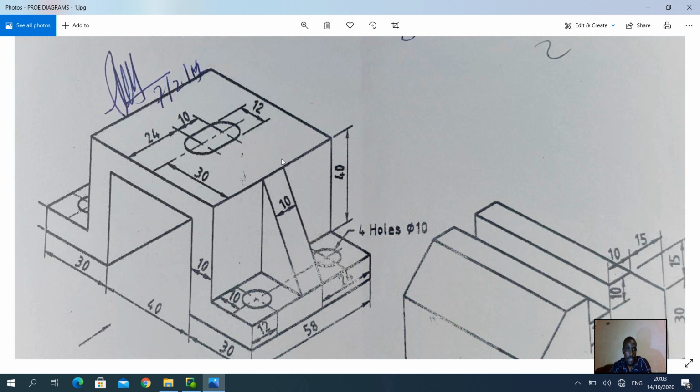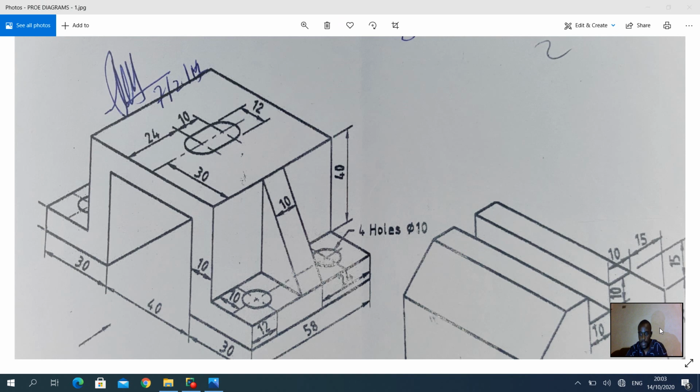So there are several ways of drawing component number 3. We can first of all draw the two-dimensional shape, ignoring the ribs here. We can draw this L shape, and then we can dimension it. But I'm going to adopt a different technique that we applied in drawing the second part of component number 4 that we started with, which is basically starting with the whole rectangle. Then I'll remove this part, I'll remove this other part, and start to include several other features in this section.